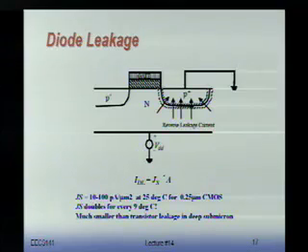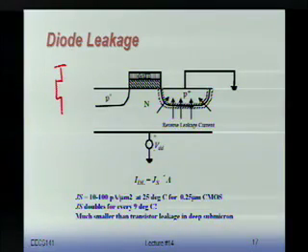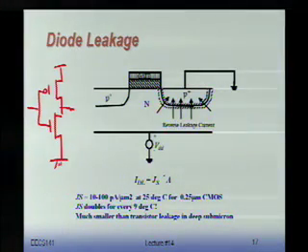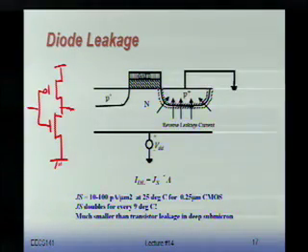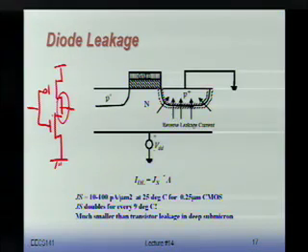Let's go to source number 3, leakage. Again, let's look at our transistor inverter. Okay, so where does leakage come from? We already know that the drain and source region of your transistor, and especially the drain region here, is a reverse bias diode. Right? In typical operation, if you don't go out to the supply rails, this is a reverse bias